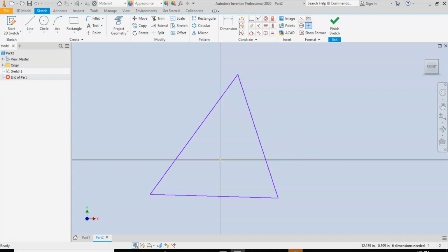So first let's look at the geometric constraints and the way that you would go ahead and assign them. As you notice, when I sketched this, I didn't lock in my lines vertical or horizontal. I just drew those in freehand, and I didn't lock in anything. So, one method of applying constraints is to apply the constraint as you are drawing. So if I've got that one there, you can see the vertical constraint is automatically locked in. As I move over here, I've got the 90 degrees. That one is going to be constrained. And then I keep on with that's a vertical, and then another 90 degrees. So those constraints are assigned as you're completing your sketch. But you can choose not to do that, depending on how you draw with your mouse.